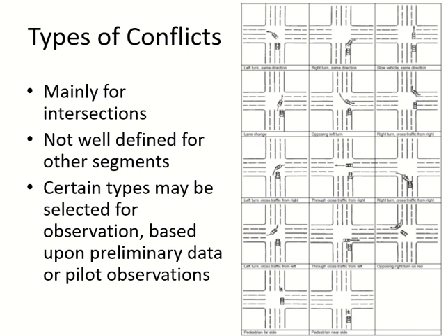Why do we put a signal or roundabout or something like this? We discussed in the previous topic as well. Stop sign or give way sign: they are there to reduce the conflict points. The conflict points are already there, like without anything. Then you will see which one of them is creating a problem, and you try to reduce them by adding an extra lane, a traffic island, a small median for turning and so on.